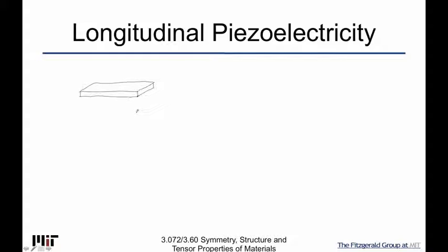And so experimentally, this mathematical case where I can't tell the difference, where I'm just measuring some areal charge, can confuse things. Here we're going to use that to our advantage, because what we're going to do is cut out a very thin specimen. Let's imagine that we have some weird shaped crystal or something. For example, we can cut a very thin slice out here, in some x1 direction, and try to measure D111 as we apply some sort of sigma 11.